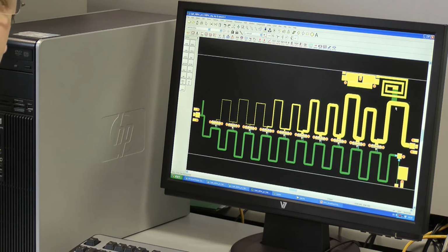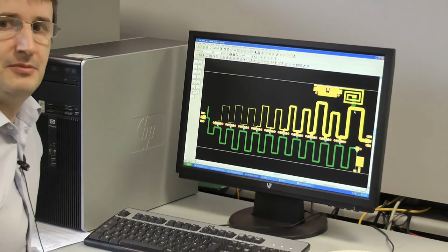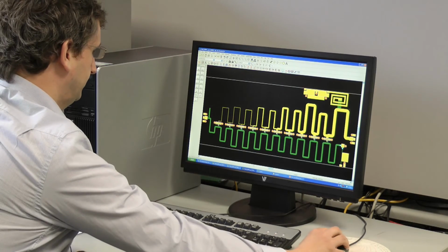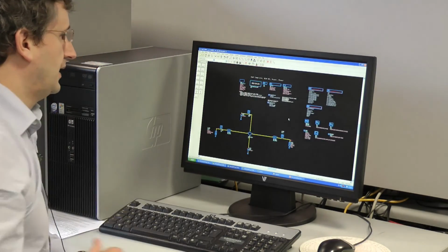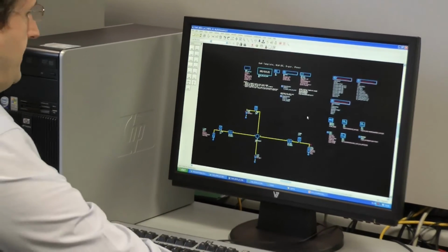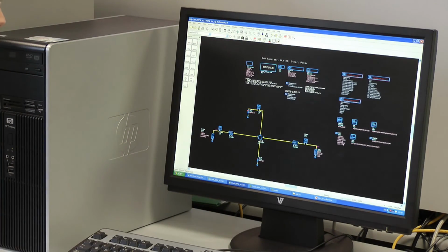We've now covered the main features of our design and the reasoning behind them, so we can now look at the simulated performance. Here is our test bench in which our NDPA design has been placed. The test bench can be configured for small signal simulations, such as S parameters useful for gain, return losses and stability. It can also be configured for large signal, such as power at 3 dB compression and the associated power added efficiency. So first we'll simulate small signal.